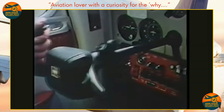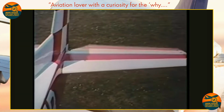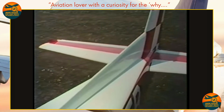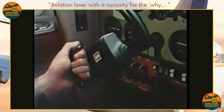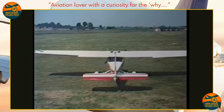Moving the control column backwards and forwards raises and depresses the elevator. Pulling it back raises the elevator, pushing it forwards depresses it. Turning the wheel operates the ailerons at the wingtips. With the wheel to the right, the right-hand aileron is raised and the one on the left depressed, rolling the aeroplane to the right. Turning it in the opposite direction moves the ailerons in the opposite sense and rolls the aeroplane to the left.